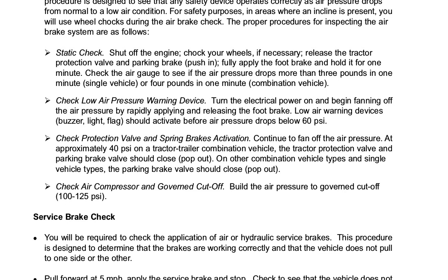Check air compressor and governed cutoff. Build the air pressure to governed cutoff, 100 to 125 psi.